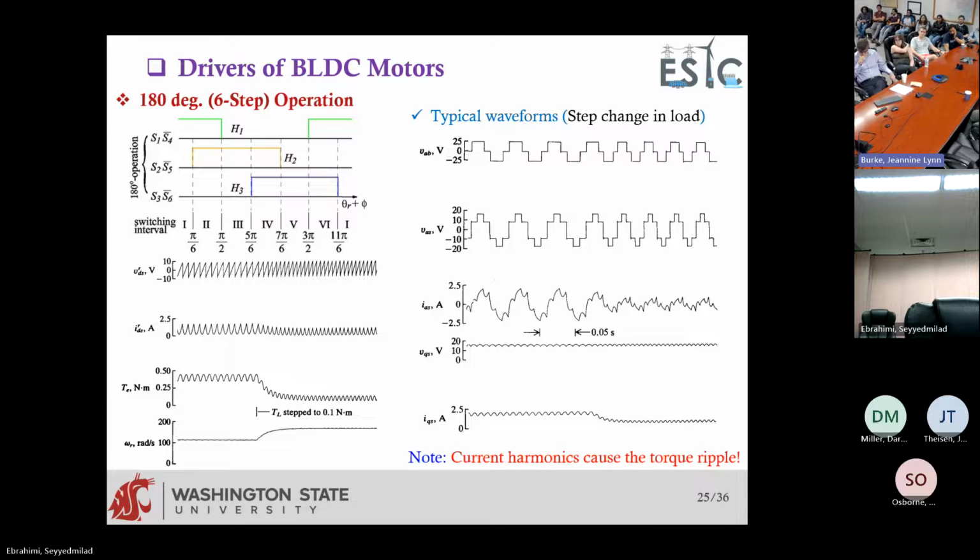One of the sources of torque ripple is the misalignment of those magnetic tablets that I mentioned. So that's one of the reasons we apply some methods. We filter the signals coming from the Hall sensors somehow to minimize torque ripple coming from them. Another reason is that the back EMF that I showed, which we assume is sinusoidal, is not actually sinusoidal. It is quasi-trapezoidal. That also contributes to torque ripple, because it's like some harmonics multiplied by some currents; if you do the math, you'll see that it causes other ripples.